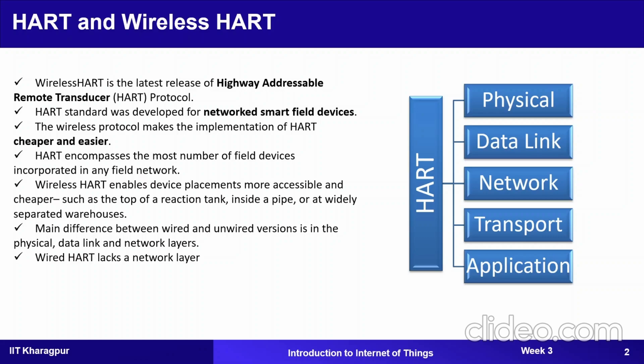If you remember, in computer networks, in order to let different users access the same channel, we have different multiplexing methods, for example TDMA, FDMA, WDMA. HART is using TDMA, and in HART the time slot used in TDMA is 10 milliseconds, and a super frame is the group of those 10 millisecond slots.